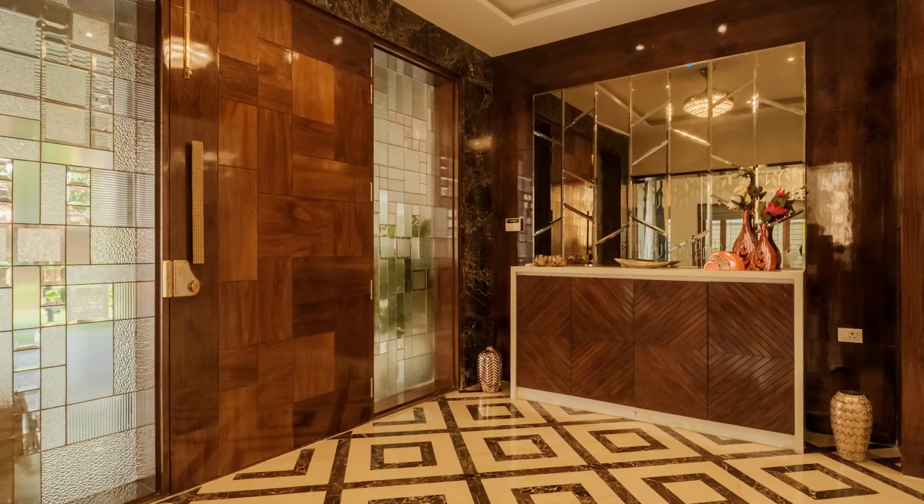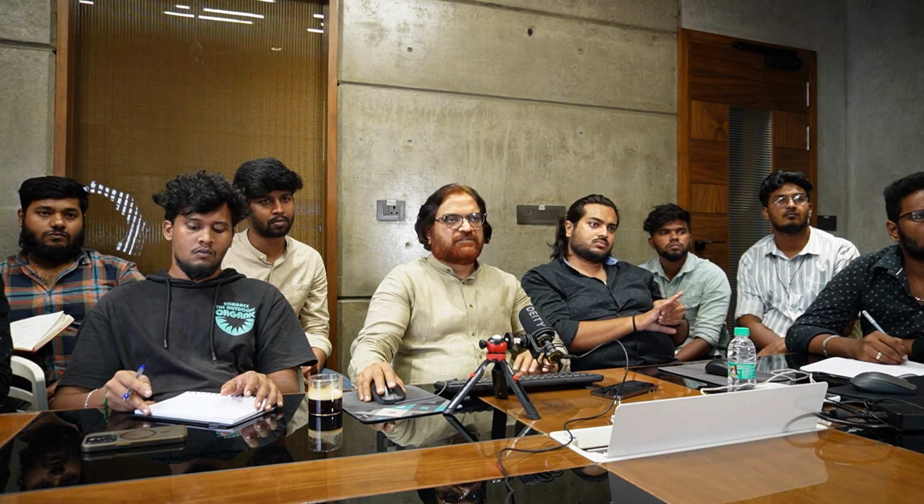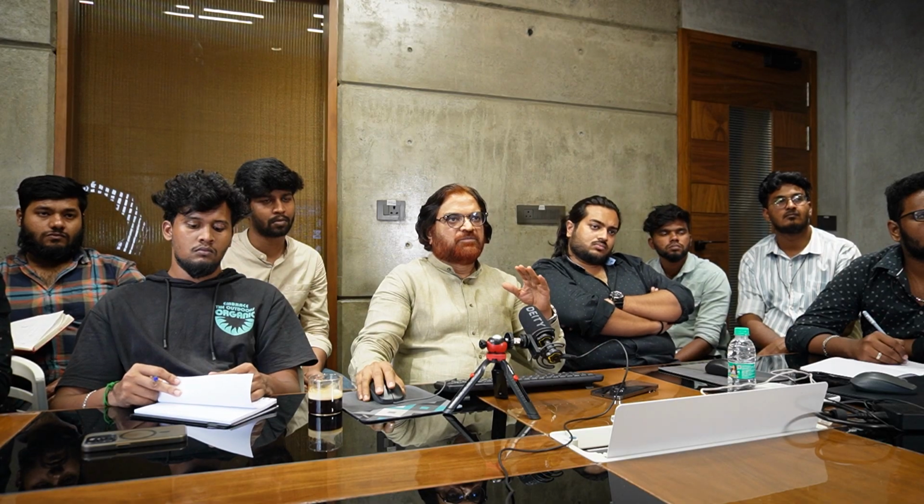So after that, we come into the house, and the living room is nicely designed. It's kind of an open plan. When you come into the living room, you will be able to see up to the dining. So one basic thing is I would like to have a provision for a partition here. So let us not fix a partition. The client is willing to have open plan, but as an architect, we should always envisage the future. So if the client suddenly asks, I want to have a partition, you should be ready for that. So that is why you should have a provision, but let us not have the partition.